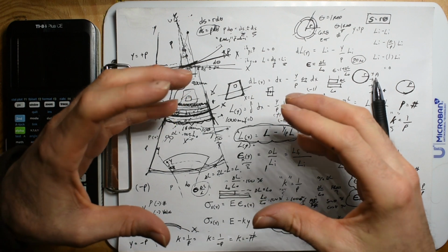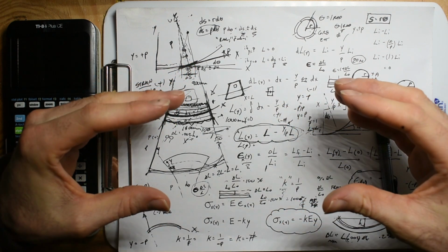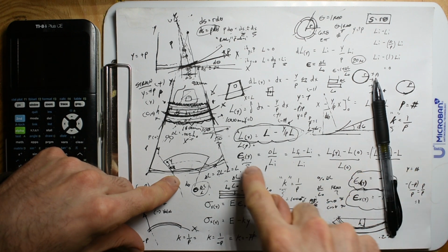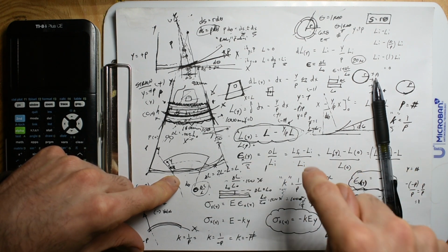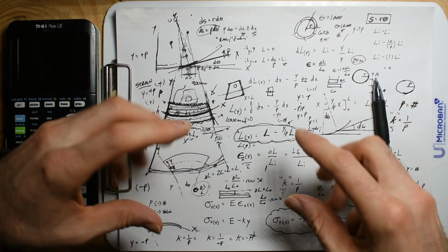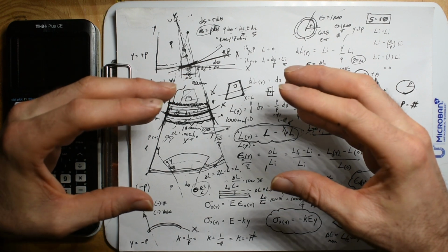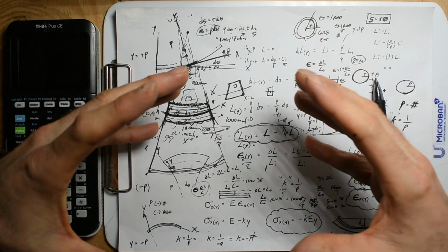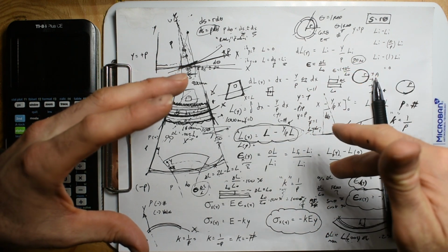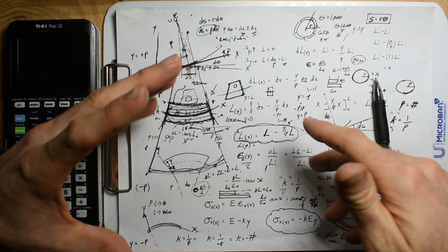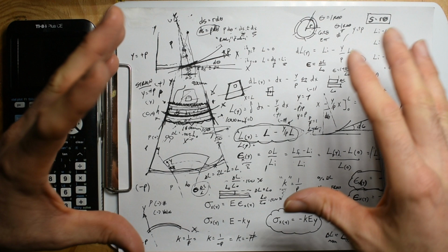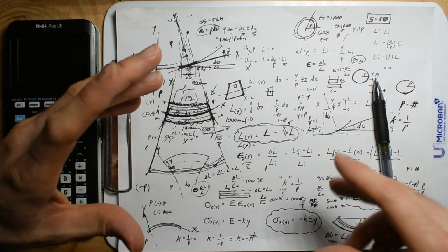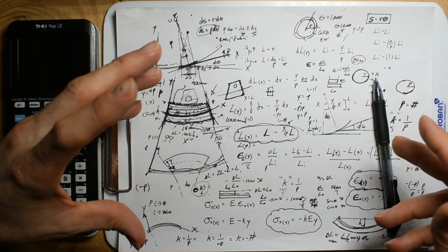I'm going to have a 1 meter bar that's 1,000 millimeters. For steel, the strain is 0.002. That means that if I have 1,000 millimeters, I can stretch it 2 millimeters before bad things happen. Basically it just becomes plastic, but you can set that as a limit of maybe failure too. Like, hey, we don't want things to go plastic because that's when it could catastrophically fail.